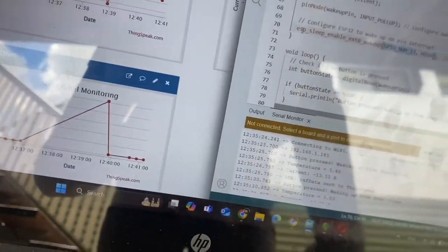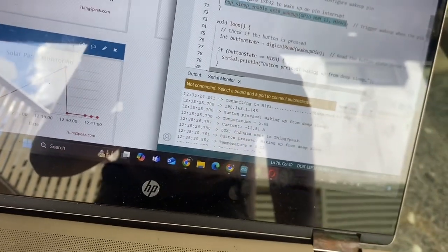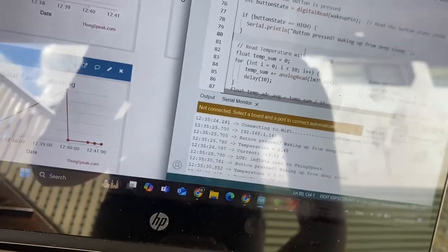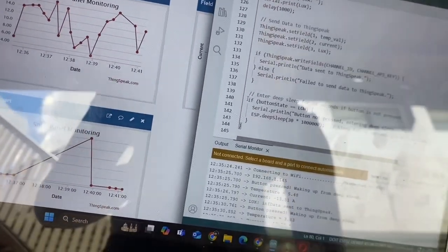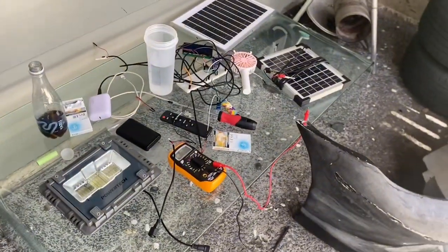And basically, the only thing you need to do to configure it is this esp_sleep_enable_ext0_wakeup, and the only thing to execute it is by doing this. Yep, this one. All right, that's all for the features, and I will see you in the next part of the video.